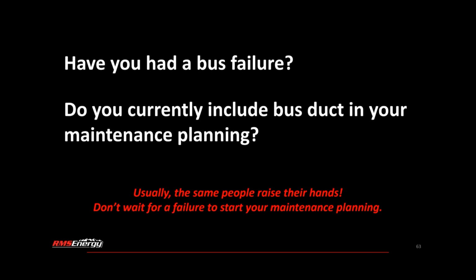So that's one situation. Another would be for a non-segregated phase bus duct. If you made some modifications somewhere, or if you had a disconnect where you can test all the way through one phase without parallel paths, I would definitely recommend that as part of your return to service practice and maintenance practices, to make sure that each phase is consistent and that there's no significant changes from the last test data that you have.